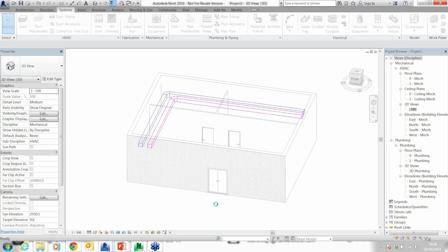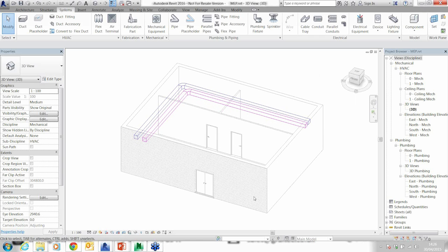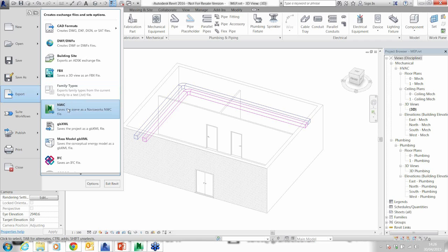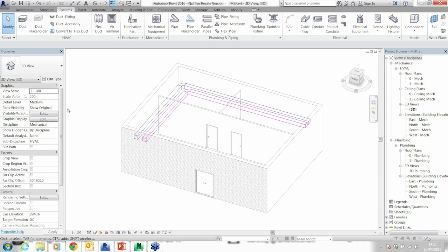Okay. So the next thing I want to do now is I want to move this across to Navisworks. Now, within Navisworks, I can just export these out as RBTs and import them in Navis as RBT. But the usual way of sharing it would be through something like an NWC. It's a very highly intelligent, almost PDF. It's a locked file format, so if you're sending this external to the company, no one else is going to actually be able to influence it.